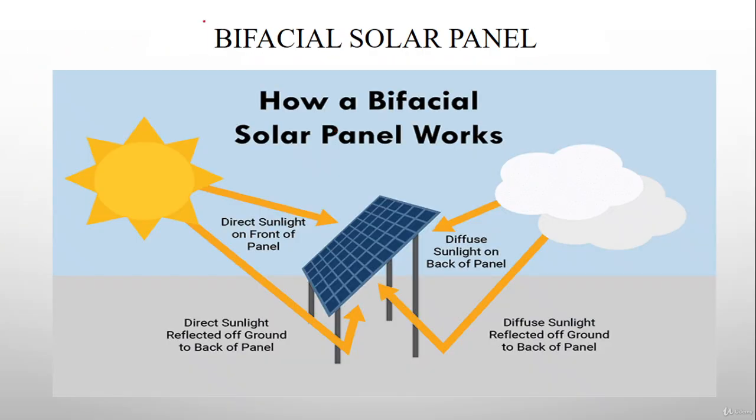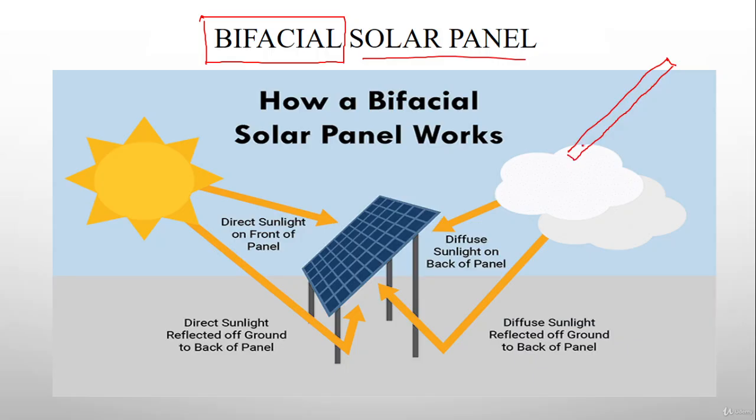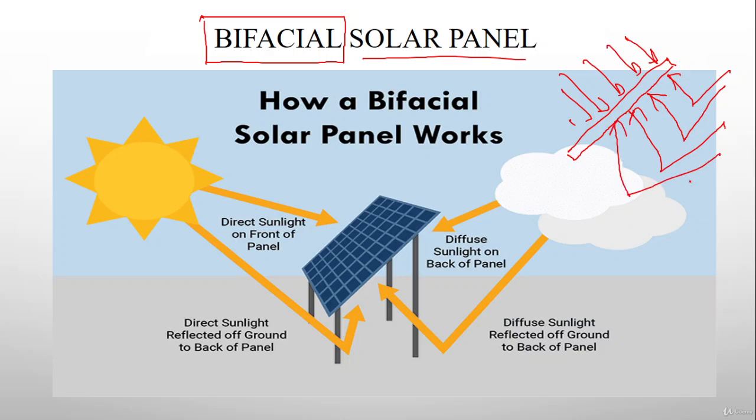The fifth and popular technology which is coming in the market is called the bifacial type of solar panel. So basically, in a bifacial type of solar panel, both faces are active for collecting photons from the radiation received from the sun. Let's say the solar panel is inclined at some tilt angle, it will capture photons from the front surface, and it will also capture photons from the reflected radiation of the sun rays. So in short, whatever the reflection of light, or the albedo of light, is utilized to generate power from the given solar cells.